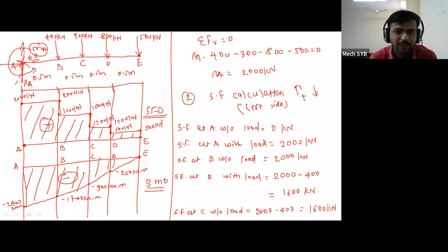The process is very simple as compared to the simply supported and overhanging beams. The cantilever beam solution is very simple, because here there is no chance of X calculation, as your SFD will be in the positive region and BMD in the negative region only. Therefore, there is no chance of SF and BM changing from positive to negative, so no X distance calculation.